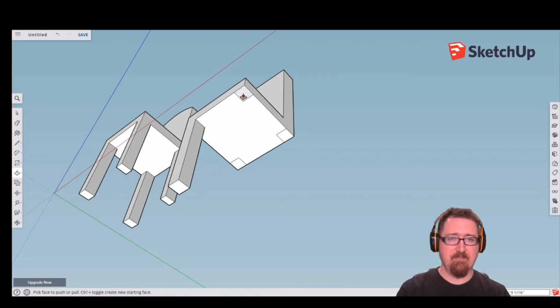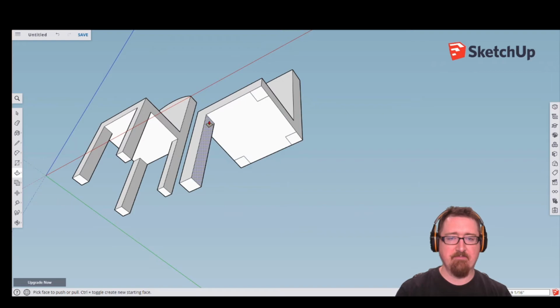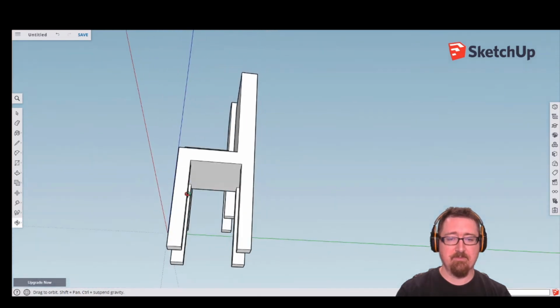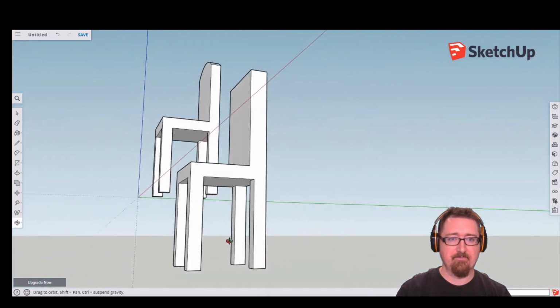And I could do that on this one, or all 3 of them, but here's a little trick that I didn't show you in the push-pull video. Okay, I've pushed this down a particular leg. If I double click on this surface here, it automatically pushes it to the correct length. So I actually don't need to infer that. So that's just double clicking using the push-pull tool.